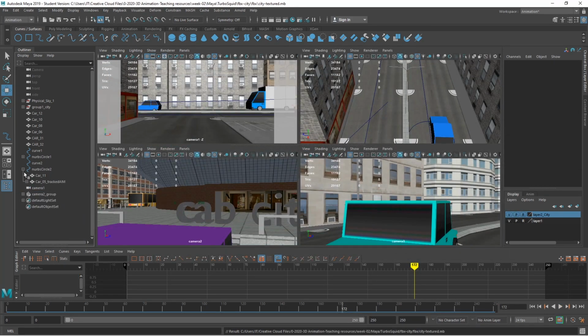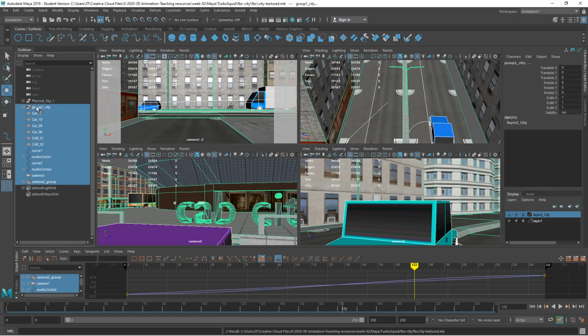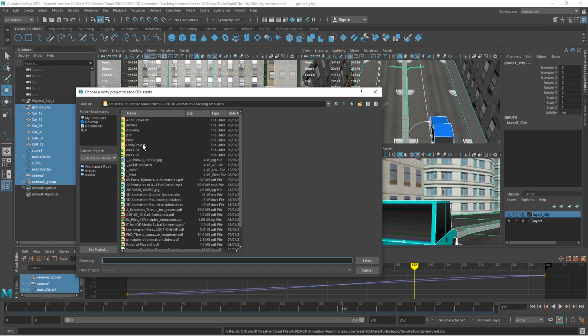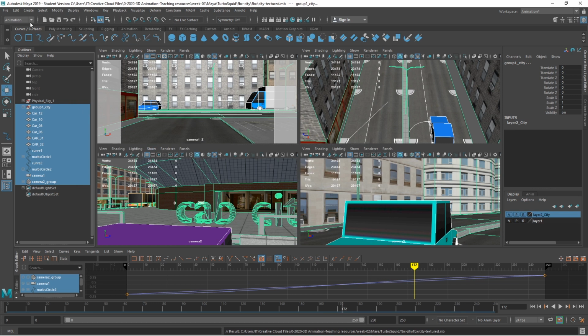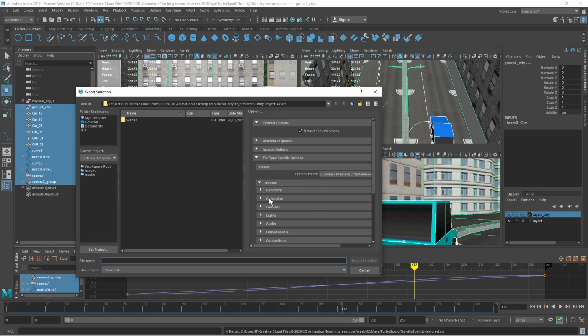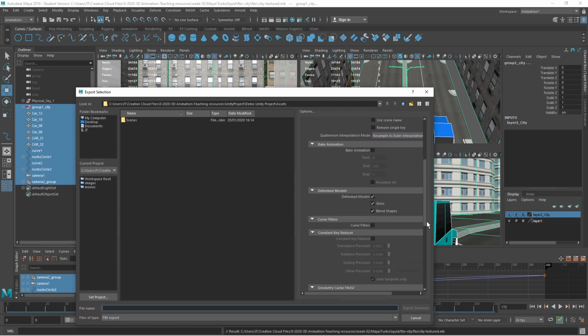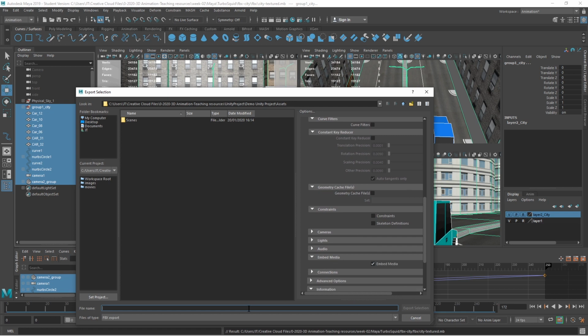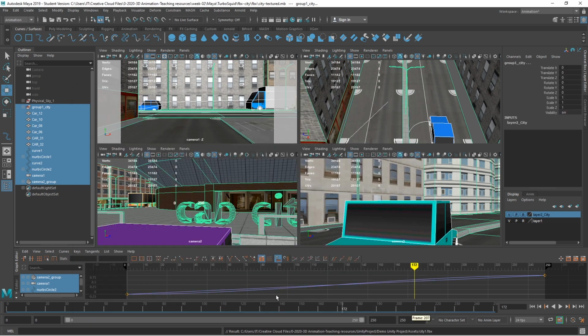Now finally I'm going to try sending this over to Unity. Some of you may have that as a workflow, so I'm selecting all the objects here, and then I'm going to go to send to Unity. So first of all I'll set up my Unity folder, which is a Unity project, so I'll select that one, and then I'll do a send to Unity selection, and FBX export animation, yes. I may need to bake the animation, but I'm going to leave that for now. And embed media. So I did spend a while reattaching all the media. So in this case, I am going to send that media across as well. Embed that into this FBX. So I'll export that. That's actually done it quite quickly.